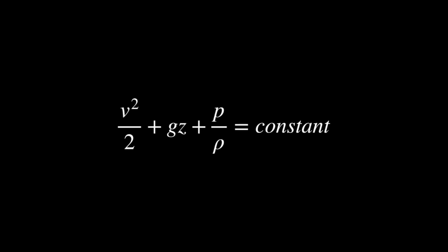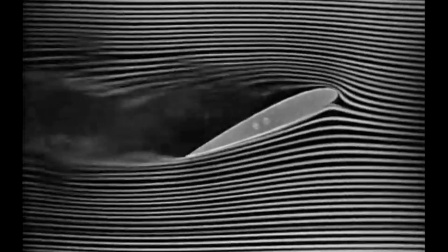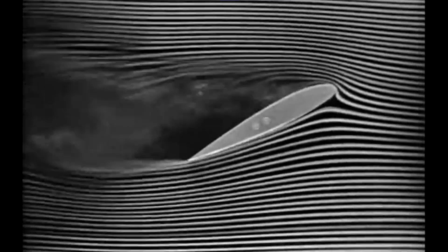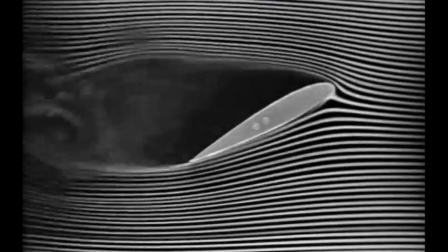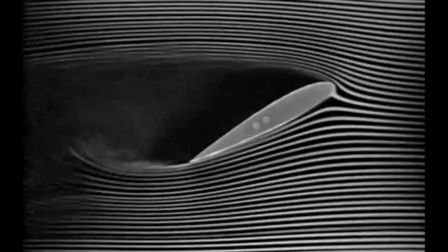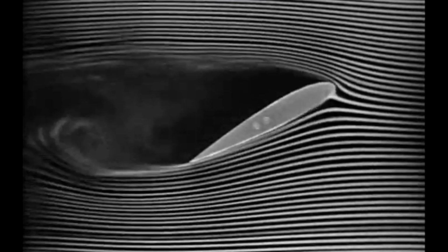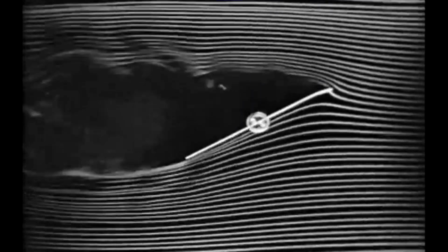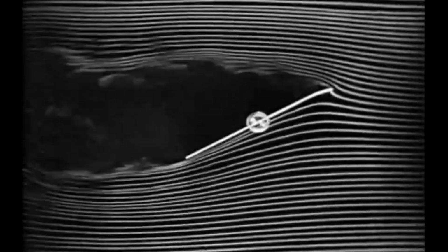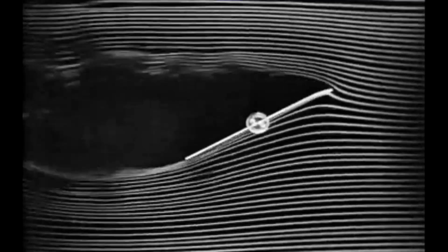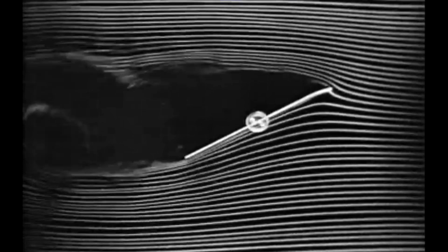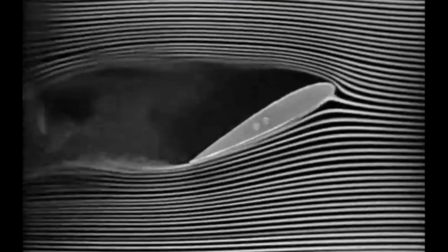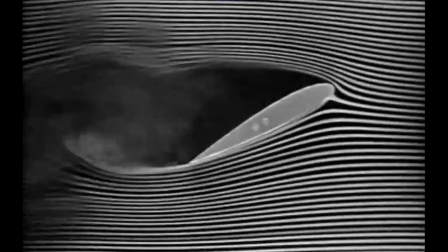When we focus on the upper surface of the airfoil, we notice that the fluid is actually moving at a faster speed relative to the lower surface. And remember that by Bernoulli's principle, the static and dynamic pressure must be constant throughout. If there is an increase in the velocity, hence the dynamic pressure, there must be a decrease in the static pressure. And so therefore, because of the geometry, the airfoil upper surface will have a lower pressure than the airfoil lower surface. This pressure differential best describes what is going on around an airfoil as it moves through a medium.